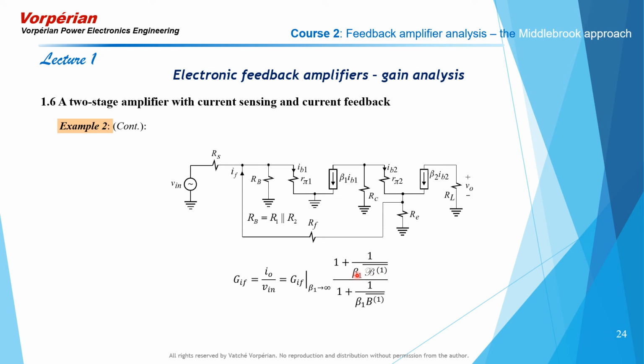In this case, the response is not the emitter voltage that is being nulled, but it is the collector current of Q2 that's being nulled. And in the denominator, we have the inverse gain with respect to beta 1 with the excitation set equal to 0. So really, essentially, most of our calculations are the same as before in the previous example.